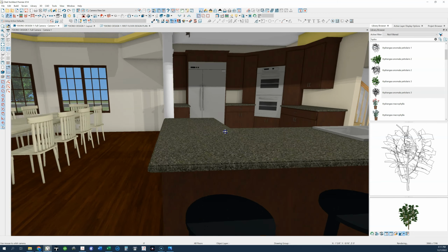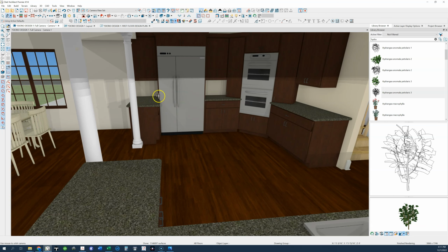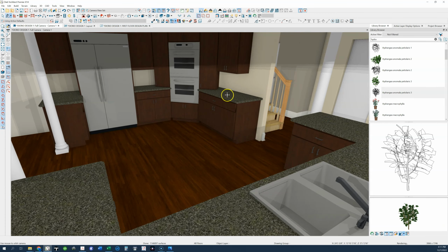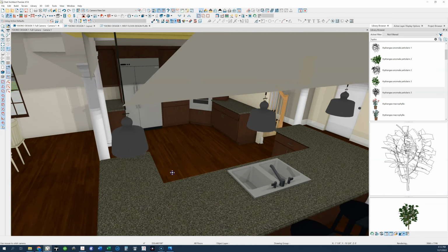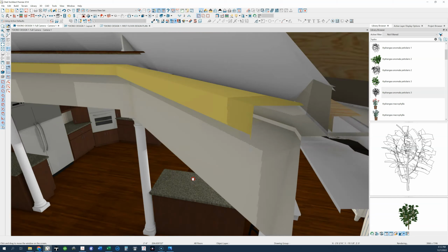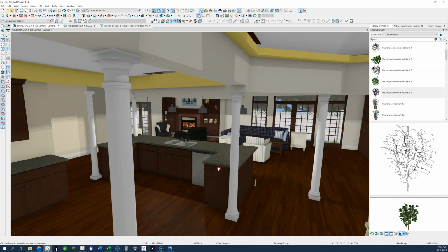You know, there are national kitchen designer minimums. You're supposed to have 18 inches minimum on each side of an appliance. If I put the cooktop here, I don't think I'm going to have enough clearance if it's an extra large cooktop to have 18 inches to the side between the oven and the cooktop. I have a couple of other ideas in my head that I just really wanted to show you where we stand right now so far with the design.